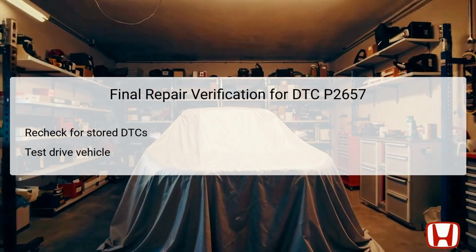After completing the required repairs for the P2657 code, it is essential to verify that the issues have been effectively resolved. Start by rechecking for any stored diagnostic trouble codes using the HDS. This step will help confirm that the system no longer indicates any issues related to the rocker arm oil pressure switch A. Following that, conduct a test drive under various operating conditions to replicate normal driving scenarios.